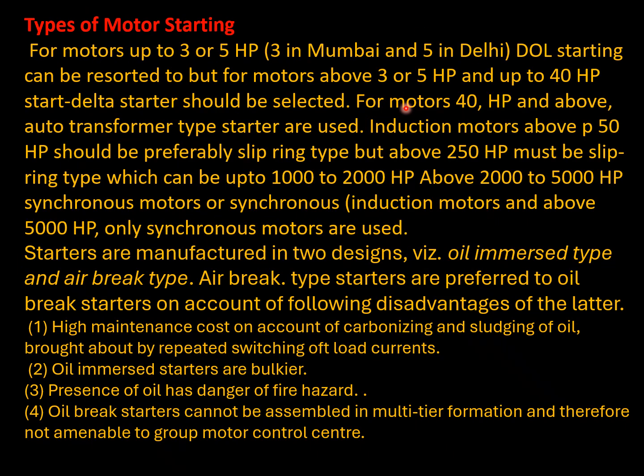Friends, now we are discussing how the induction motors can be started. For motors up to 3 to 5 HP, direct online starting can be resorted to, but for motors above 3 to 5 HP and up to 40 HP, star delta starter should be selected. For motors 40 HP and above, auto transformer type starters are used.